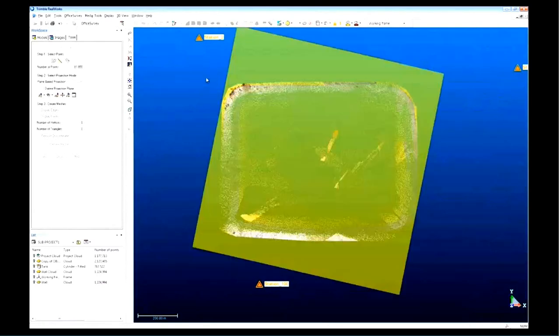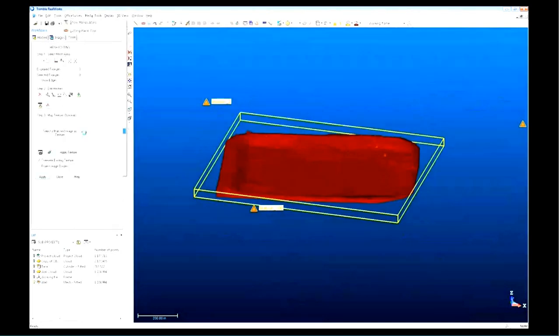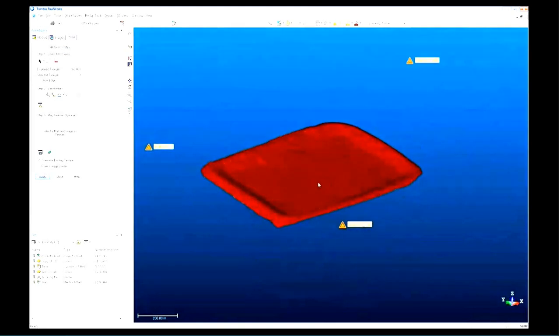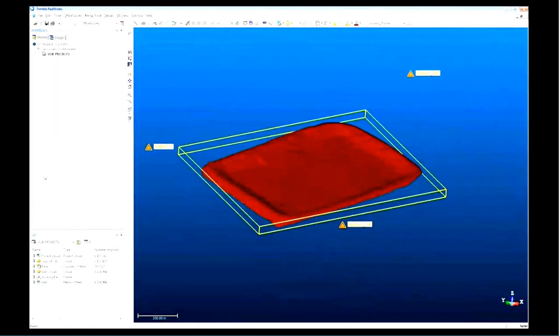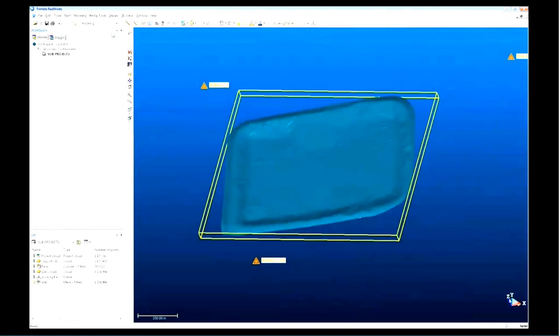So I'm segmenting around just the area of my retaining wall that I'm interested in, and create that, do some quick editing to smooth out, get rid of the rough edges on this mesh. Maybe there's some tumbleweeds growing or something. It'll smooth those out. Changing the color so it's just easier for me to see.